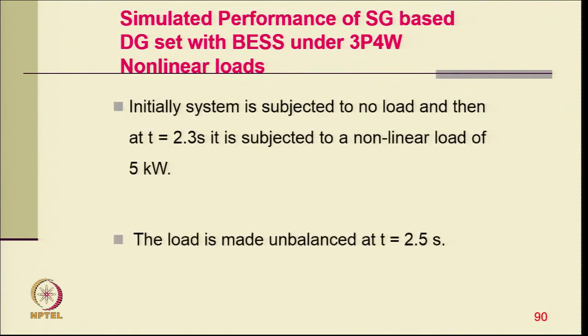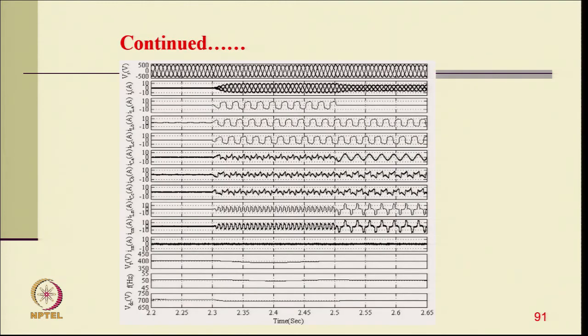And then we go to the non-linear load. So, here you can say there is no load, but we have 3 single phase non-linear loads. Here we are providing even the neutral current compensation. So, the generator neutral current is 0 and your compensator fourth leg is providing the compensation of neutral current, as you see in the opposite of these, and these are the 3 typical compensator currents. There are 3 load currents and one phase load is removed.